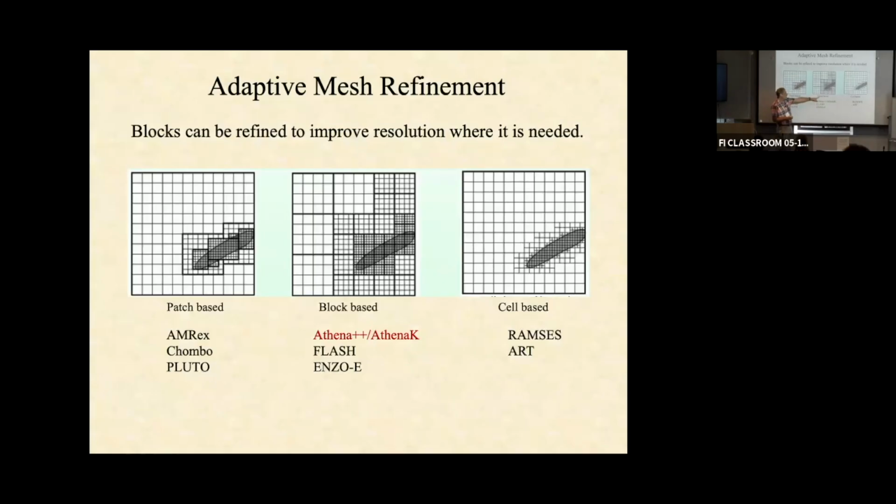Or you could use the so-called block-based AMR, where the background computational domain is broken up in individual blocks, kind of like this domain decomposition, in this case into a 3x3 mesh of blocks. And then you're only allowed to refine a given block. And so this 3x3 block would need to refine these 5 blocks, and then these 4 could be further refined, and so on and so forth. As you can see in this example, it leads to a much larger volume being covered with finer cells. So there's many, many more cells that you generate in this process.